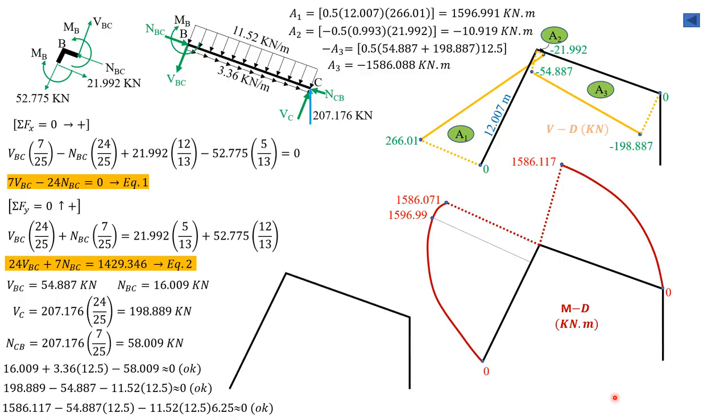And for the elastic curve, we have positive moment here. So it looks like that, concave up with respect to this inclined member. So it's like that, concave up, then slanted, because there's no moment here. So concave up, then we just make this portion slanted straight like that.